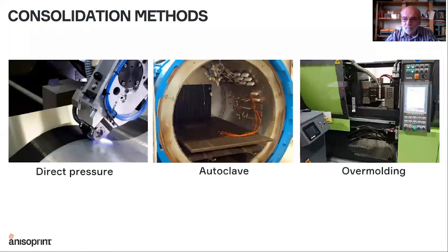And if you are trying to make something like a thin wall or complex 3D structure, this roller pressure might ruin the structure. So it mostly limits the potential shapes that you can manufacture with a pressure roller to thin sheets.